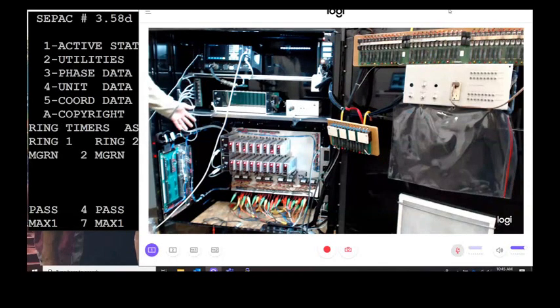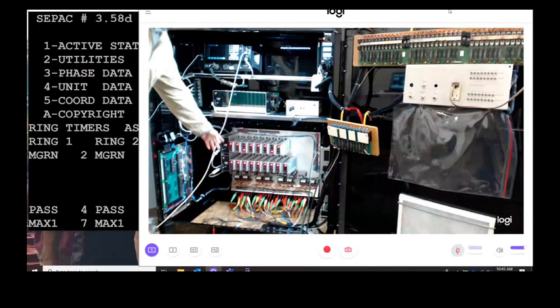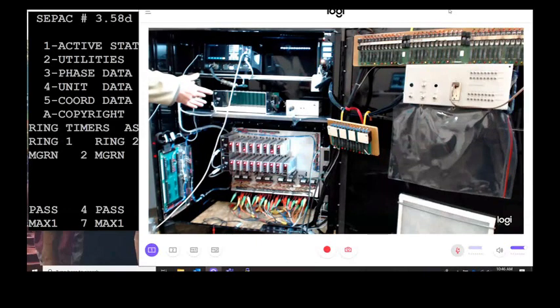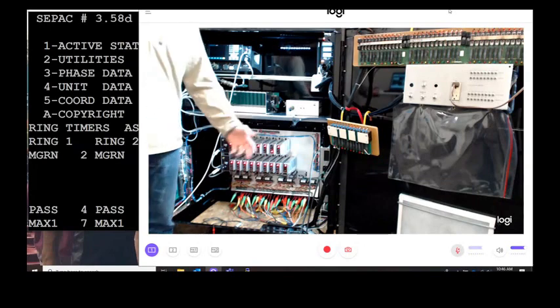So stop time basically means that we stop the controller in the time or the sequence that it's at. Right now, if I look at my load switches, I know it's hard for you to see, but I have a 3 green and a 7 green. 3 green and 7 green are typically on my side street left turns. So they're on together. Basically we had a conflicting movement light up. So now we're going to troubleshoot to find out what that is.